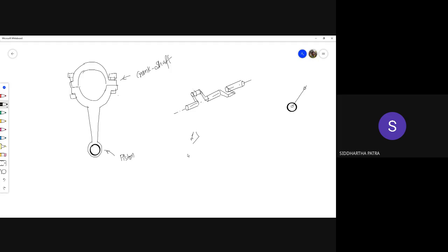First of all, when the piston is moving, when the shaft is rotating, or rather when the vehicle is running, or when the IC engine is operating, the net inertia of the system is affected by the inertia of the piston, the shaft, the flywheel, which is not shown here, but also that of the connecting rod.